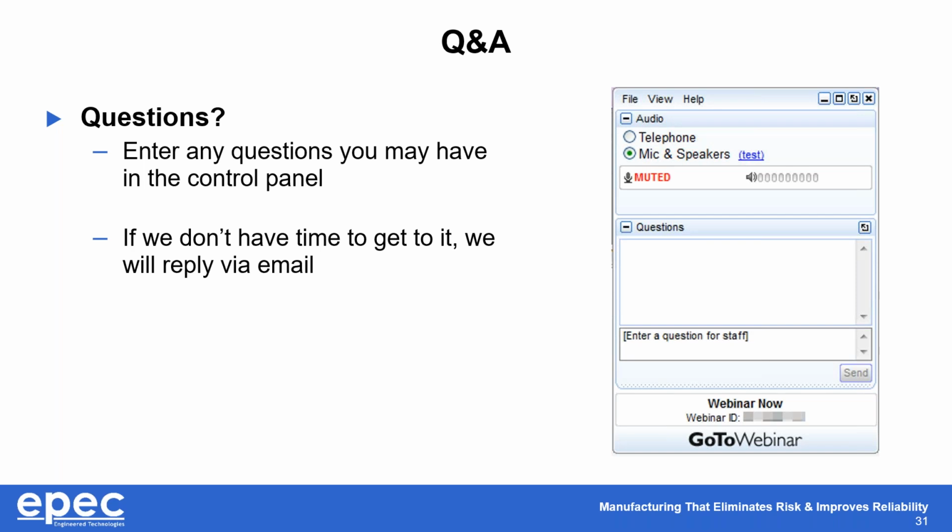So supporting our customers with that part of it is a big part of what we do. We'll create Gerber files, submit that back to the customer so that they can visually see exactly what's required, giving them an opportunity to either move forward as is at a Gerber stage level or go back into their CAD system and implement the requirement.